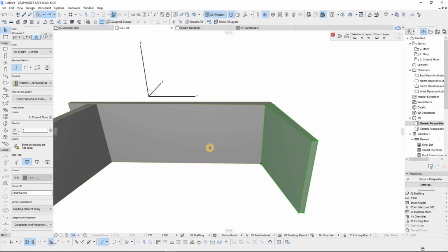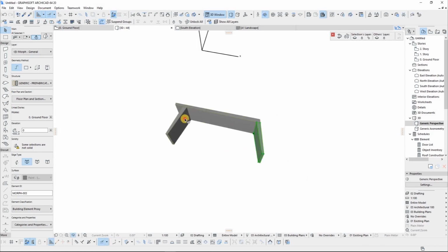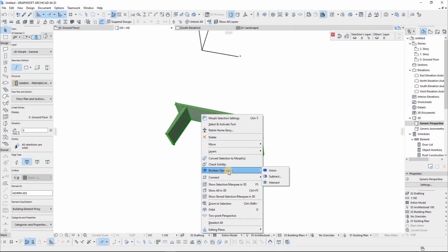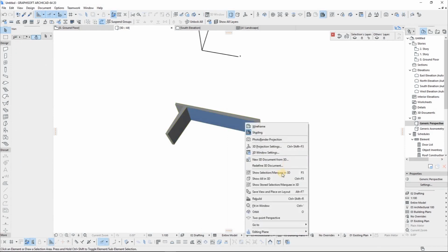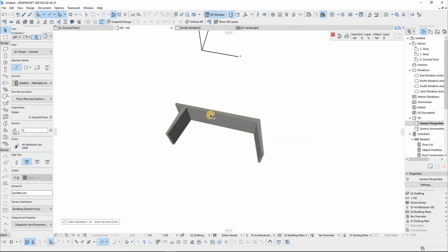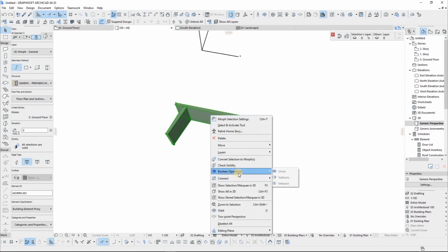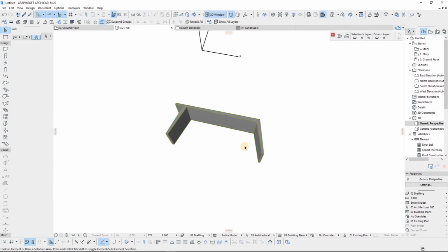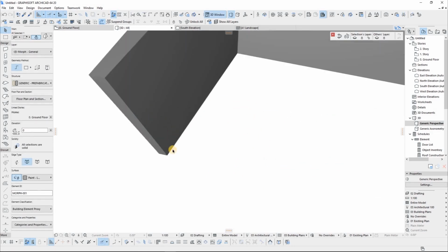Now that I have my table shape formed, I'm gonna go ahead and select all these morph tools that I've created, and then I'm gonna right click them. So what I did is I right click. In fact, let's go back because I think I just went too quickly. Boolean operations for the morph tool obviously. And then I'm gonna click union, which is going to unite them, so that now I can Control E, rotate.